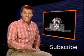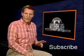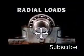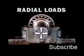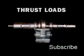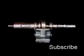Bearing designs differ depending on the type of load they're designed to support. We're going to discuss the two types of loads that bearings can be subjected to: radial loads and thrust loads. Radial loads are forces that act along a radius of a bearing or shaft. This rolling element bearing is designed to resist a radial load. Thrust loads, or axial loads, are back and forth forces exerted on a bearing or shaft in a direction parallel to the axis of the shaft. Now take time to see some bearings designed to resist thrust loads by selecting Next. We've seen how rolling element bearings are designed and how lubricants reduce friction in rolling element bearings.